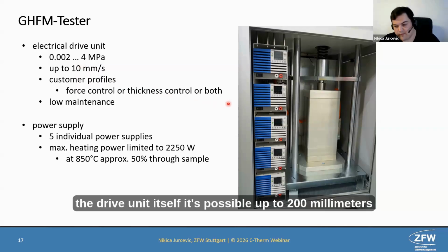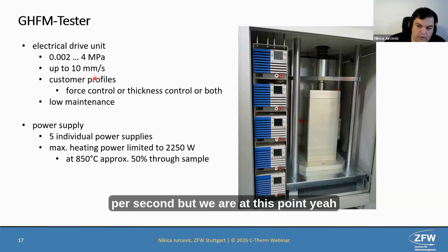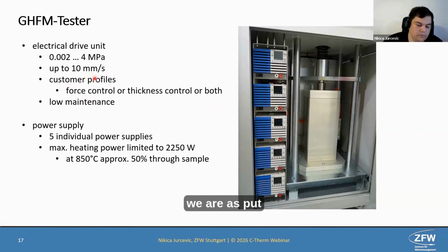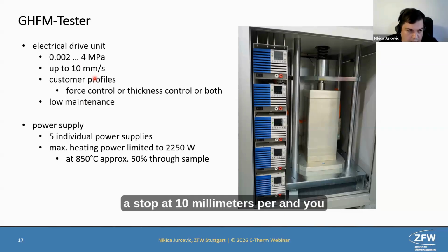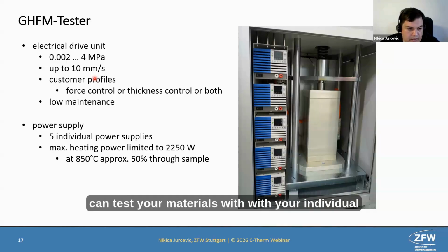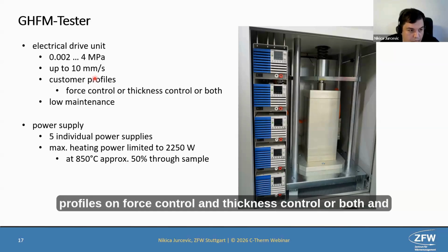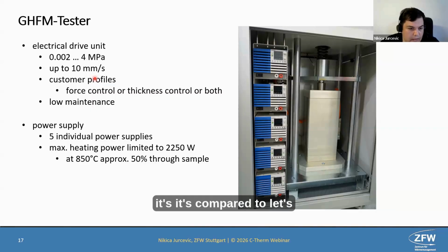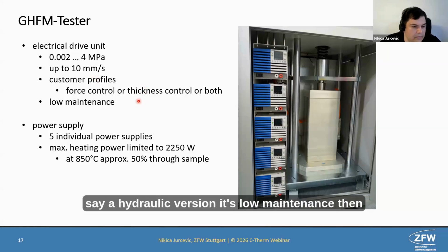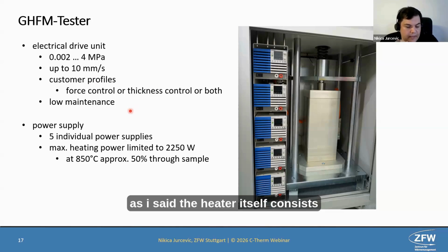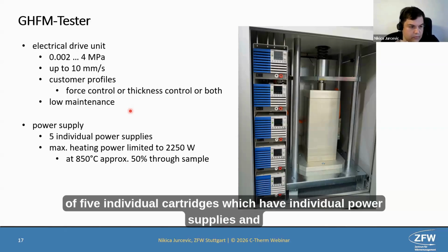The drive unit itself is capable of up to 200 millimeters per second, but at this point we have put a stop at 10 millimeters per second, and you can test your materials with your individual profiles on force control and thickness control, or both. Compared to, let's say, a hydraulic version, it's low maintenance. As I said, the heater itself consists of 5 individual cartridges, which have individual power